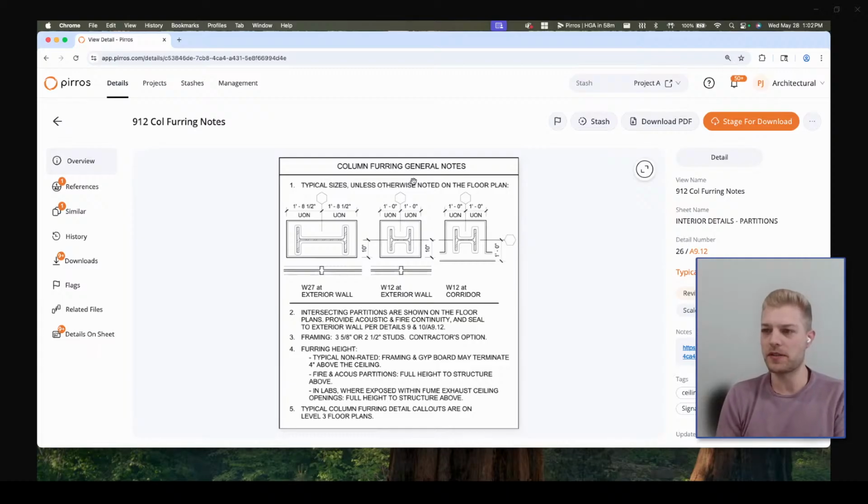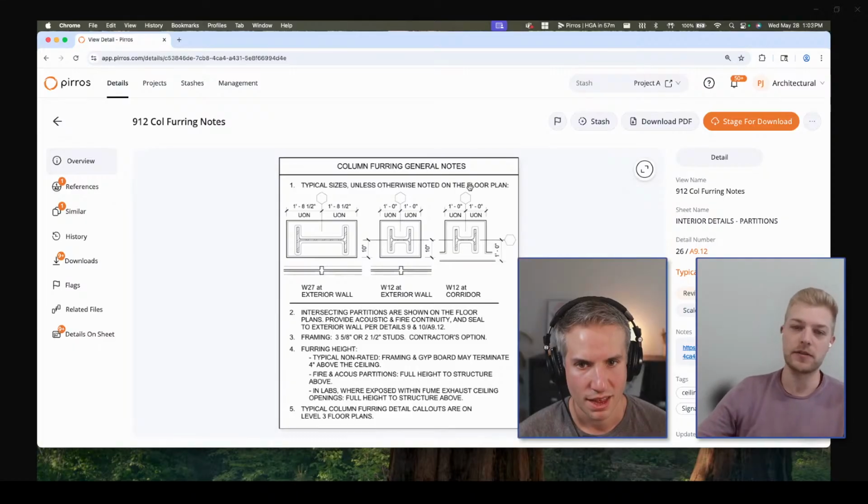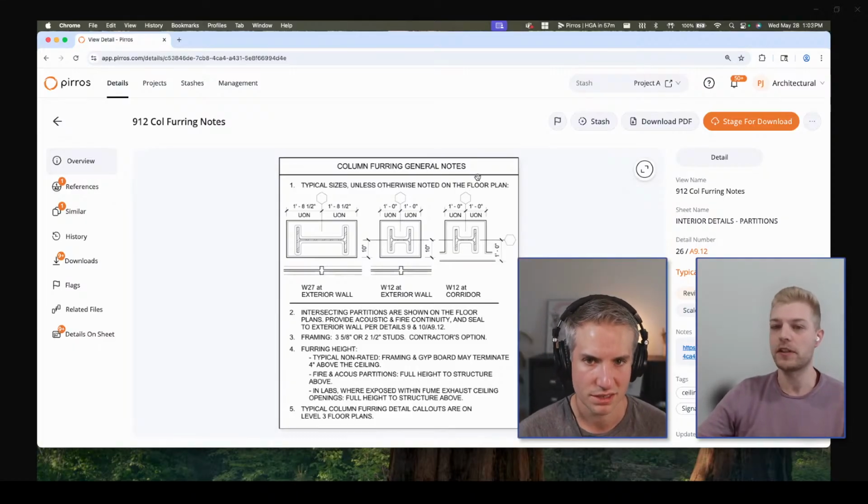And you probably saw it earlier when you download a detail into a new project, even if it is in an earlier version of Revit, that upgrade time is so quick because we've already segmented it into one drafting view. So you don't ever have to upgrade a huge model or open up a huge model anymore. You can just quickly pull it into your project. It's a split second to upgrade that detail. But yeah, every detail that you see here, both a .pdf and .rbt file.